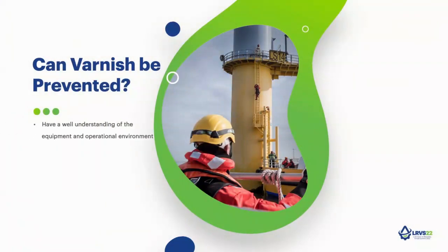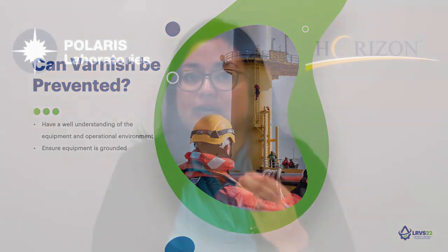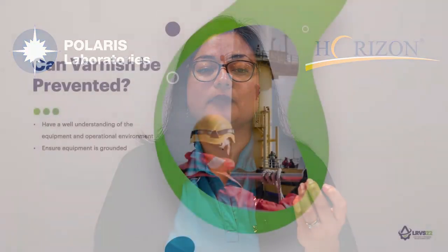Have a good understanding of your equipment. Get to know the owner's manual, the manufacturer's manual. There's a lot of information in there about the maintenance and the care that is needed for that component. Ensure that your equipment is well grounded. I cannot stress this enough. Ensure that it's well grounded and that you have the proper anti-static filters installed in your system, because static electricity can cause varnish to form.